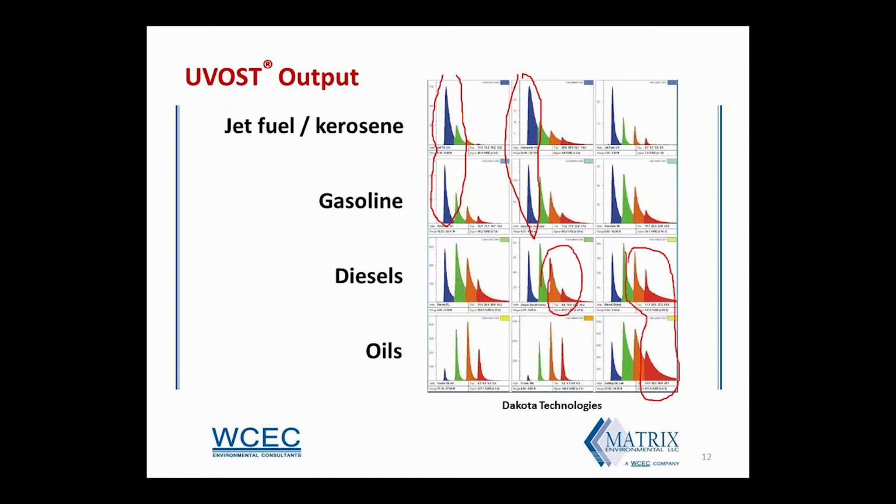I'm not very good at drawing with my mouse, so pardon the crooked lines there. At older release sites where the LNAPL has become weathered, you may see a shift in the waveforms more towards the right, and that's something we call red shifting. Our operators are really quite adept at identifying the subtle differences in these waveforms out in the field and examining the waveforms throughout the course of the project, and sometimes reveal the presence of commingled plumes or new or unexpected